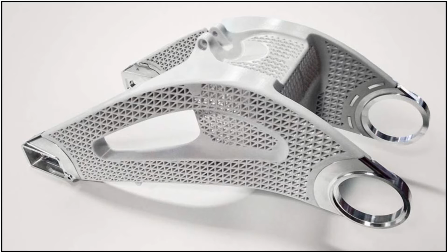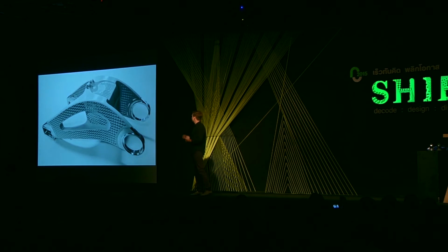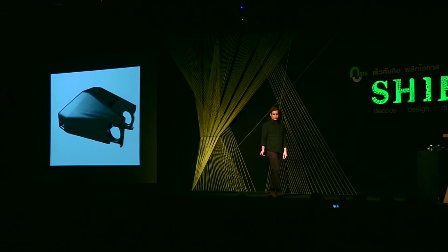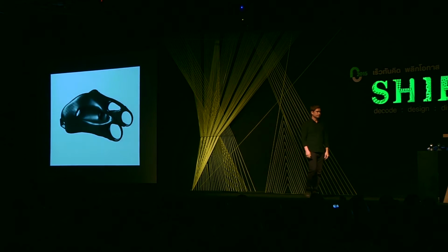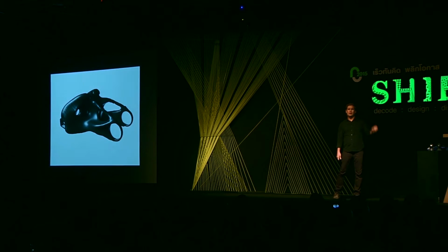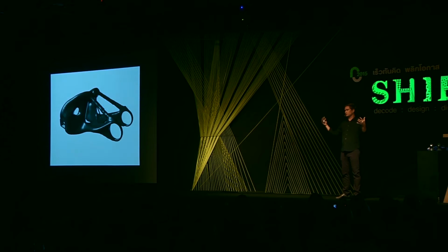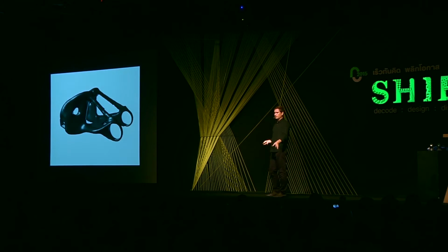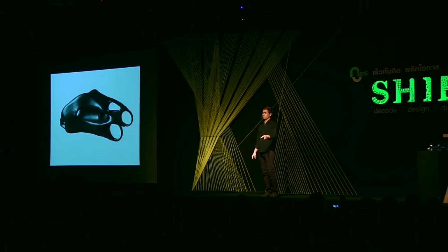This is machined aluminum out of a block of aluminum, so we minimize the amount of material that we wasted. And it was much lighter and met the requirements of the original structure, but we're like, you know what, we can do better than that. Let's get machines involved. So we used a technology we call Dreamcatcher to shave away, carve out all the material that we didn't need. So you remember the heat map, that structural analysis with the red and the green and the blue? This basically took away all of the blue areas, because it's structure, it's material that we don't need.